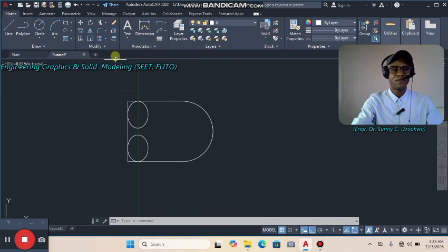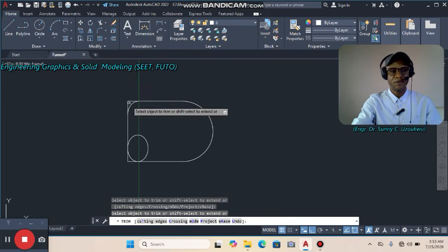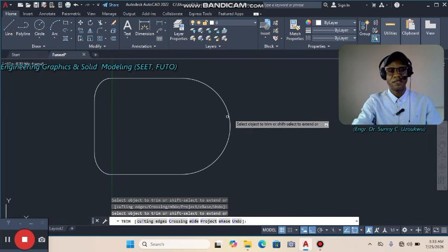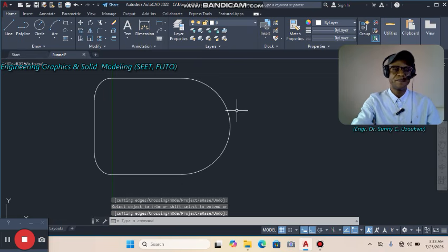Okay, so having gotten what I want, I'm now going to trim as displayed on the modify panel. Select it, then trim all the places you feel that are not relevant. As you can see, now you've got that, and that is that, and that is that, and that is that. So I've gotten it. It gives me very smooth curve, both on the left and on the right side. So that's the essence of what I've done now.